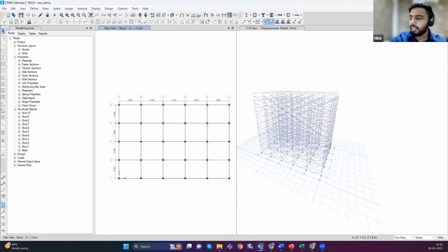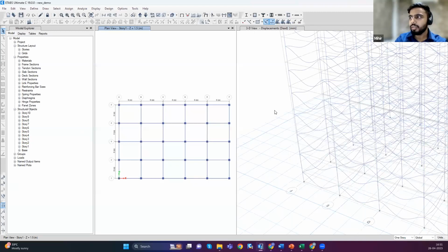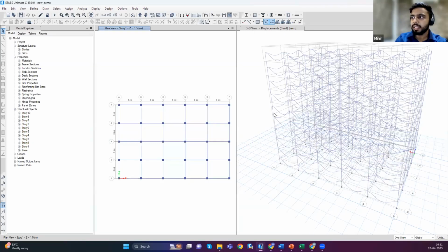I would say it will depend upon the geometry of the bridge. Suppose I'm having this kind of geometry where there is no irregularity, I'm pretty sure the hinges will be formed at the ends. That is why we have made it in that manner. But suppose there is some irregularity or some connections at intermediate locations as well, then we need to provide hinges there as well, where the mechanism can be formed. Okay. So currently for the beams and the columns, we are providing them at the ends, right? Yes. Okay. And suppose we are also modeling the infills, then we need to provide the hinges accordingly. There may be axial hinges in such a case. Yes.